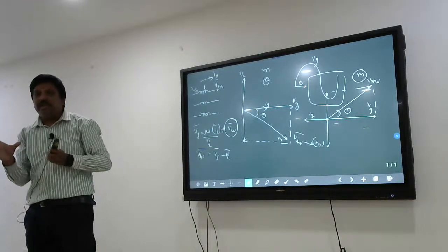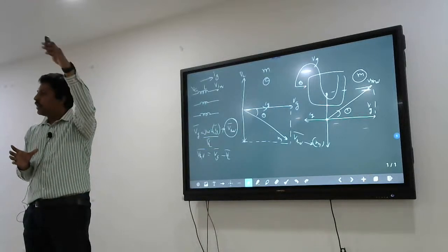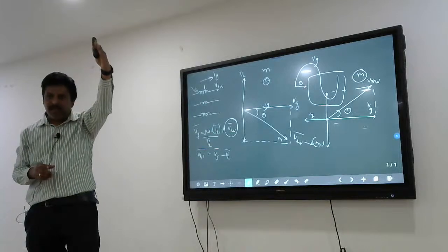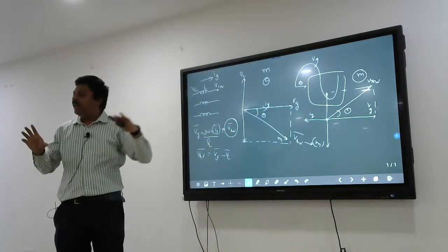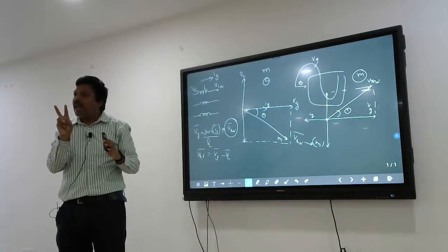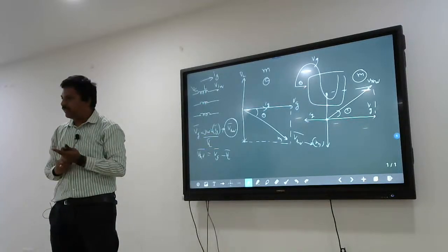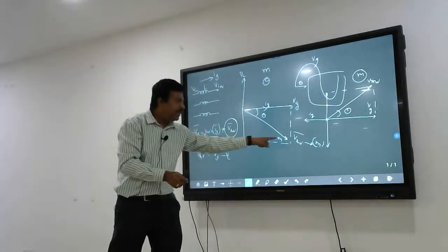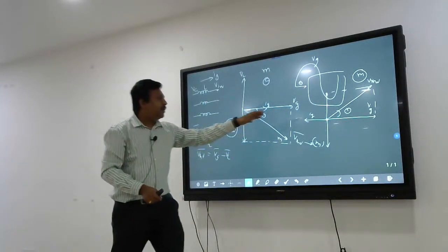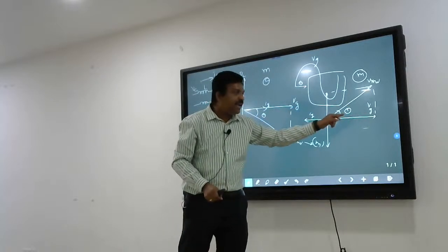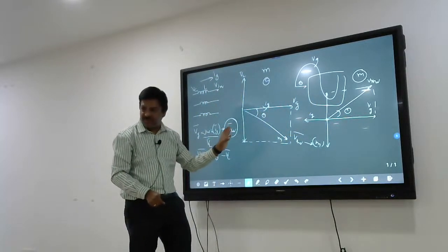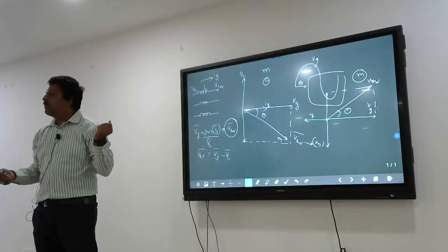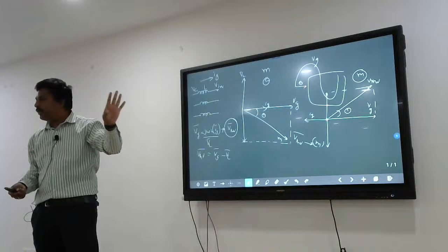That reference voltage is reflecting the actual voltage. If the reference voltage is a sine waveform, the fundamental of the actual voltage is a sine waveform. So the inverter output is also a sine waveform, but in this case there are two parameters: one is the modulation index, the other is the phase shift. If you give a leading phase shift and the required modulation index to get this magnitude, then you are trying to inject power into the grid. So this is the leading phase shift. If you have a lagging phase shift with this modulation index, we are actually taking power from the grid. So the vehicle-to-grid and grid-to-vehicle concept is covered.